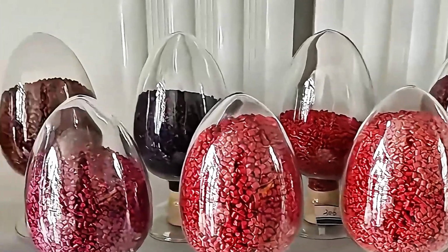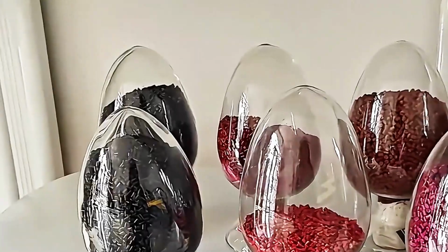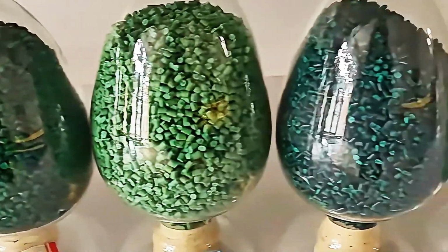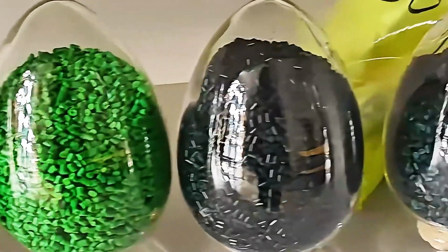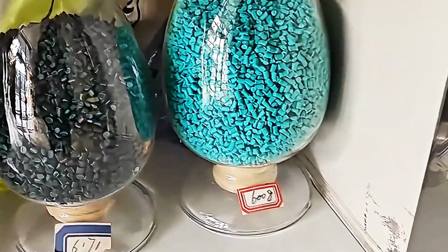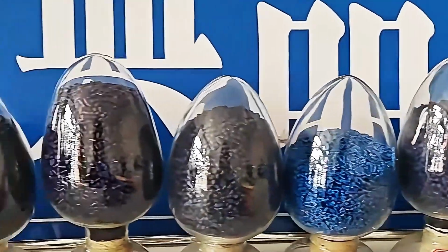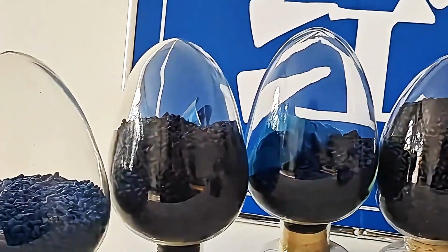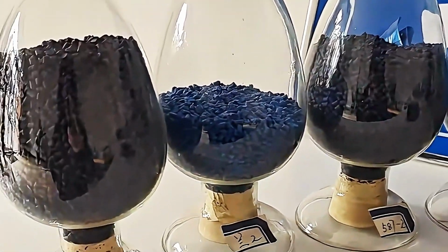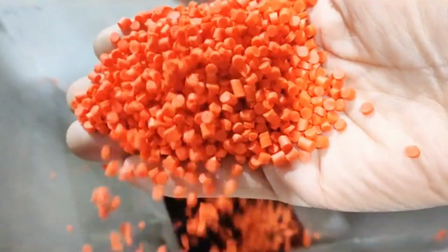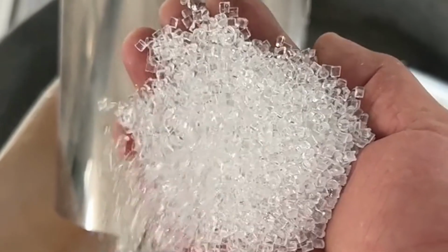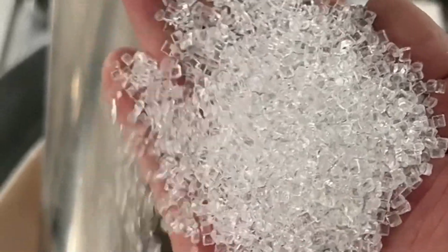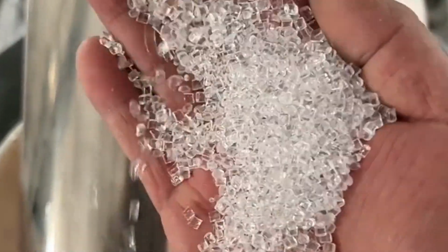Select appropriate plastic materials. The selection of plastic materials has a decisive impact on the performance and cost of the parts. Different types of plastics have different properties, such as strength, toughness, heat resistance, and chemical resistance. For example, polycarbonate (PC) has good transparency and impact resistance properties, and is often used in the manufacture of spectacle lenses and automotive headlight covers, while polypropylene (PP) has good chemical resistance and fatigue resistance properties and is widely used in food packaging and injection molded containers.